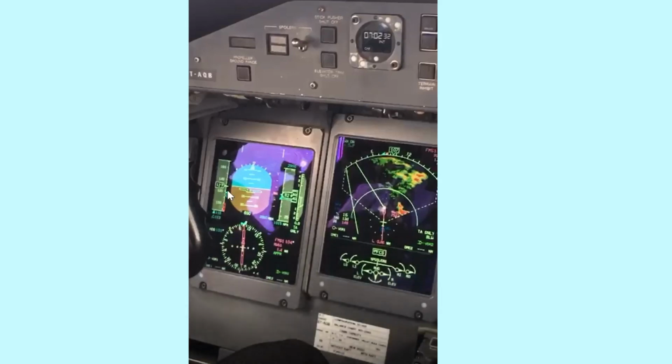So the VREF is this marker here, this solid blue triangle, and that's 118 for this landing weight of 27 tons. And if I kept my torque the way the autopilot was keeping it, and when I took over I didn't disturb the autopilot's setting which was given to me, I kept it just the way it was. That's how we set the torque, based on the first 2 digits of landing weight, and that will make your speed VREF to VREF plus 10, somewhere here.